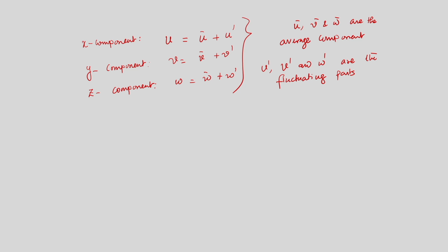Now, if we recall the hot wire anemometer, which I discussed in the context of thermal anemometry, we have seen that thermal anemometry is essentially a measurement technique to measure flow velocity by measuring the heat transfer, that we have discussed.